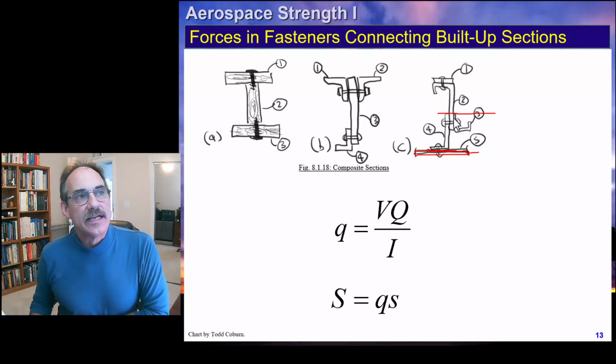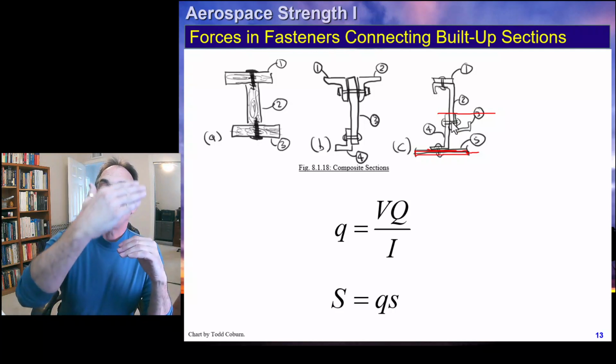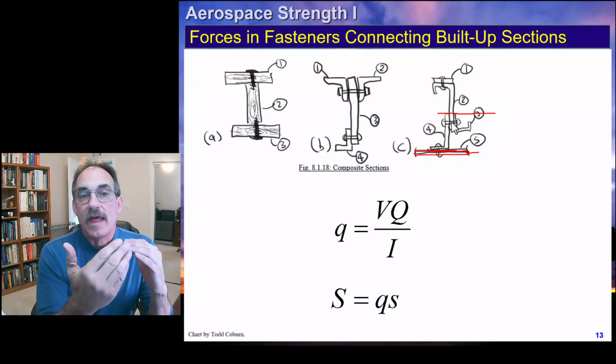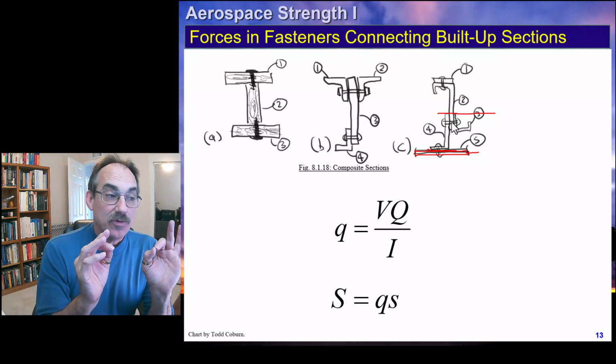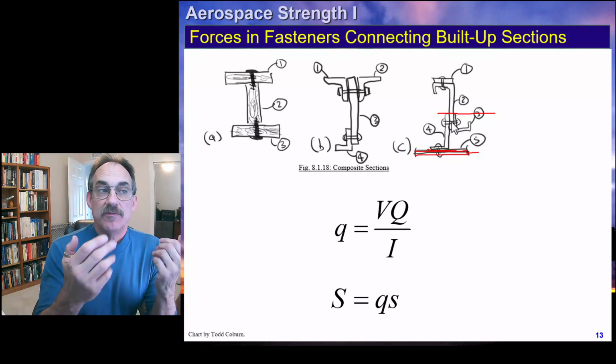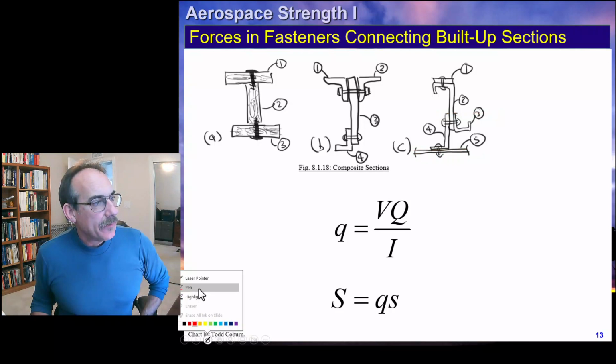Now, with this, while y matters positive and negative when we're adding or subtracting from another piece, whether that shear flow is coming into the page or out of the page, we normally just ignore the sign of that. We're looking for the magnitude of the shear force in the fasteners to evaluate the strength. That's how that is done. You got that? Okay.